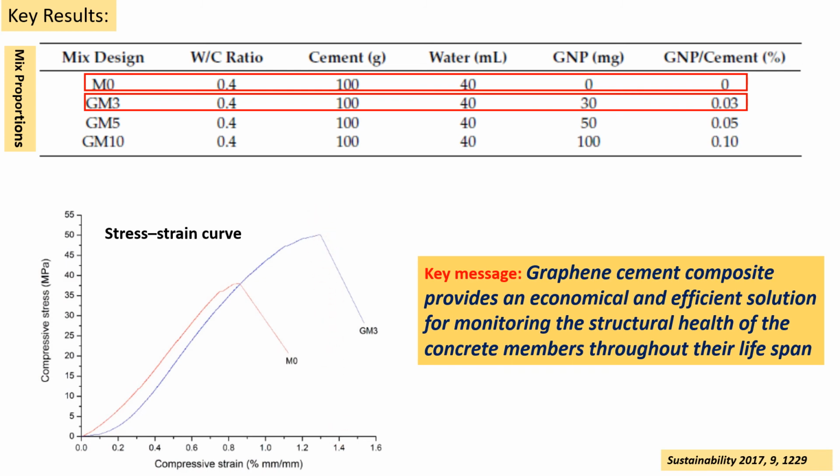So definitely the compressive strength and overall performance of the cementitious composite increases by adding a very minute dosage. That enables a very economic and efficient solution to design and develop a good cementitious or concrete composite with graphene. That again proves the same story: graphene material is quite effective in improving the mechanical property.